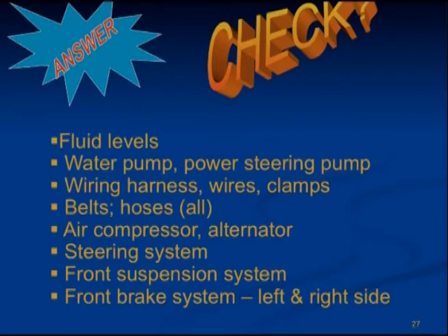Okay, check for excessive oil or grease deposits. Check the fluid levels to include engine, transmission, coolant, power steering, power brakes, and washer fluids. Check the water pump and the power steering pumps. Check your wiring harnesses, wires, and clamps, and check for wiring insulation.